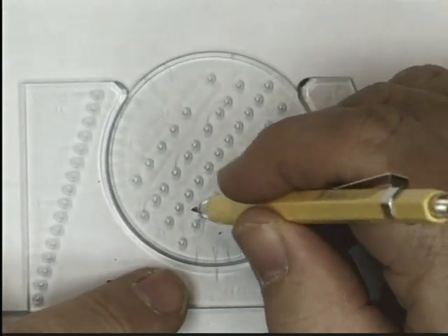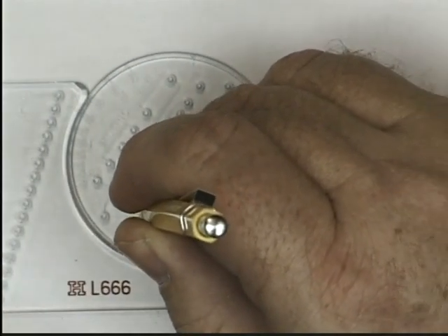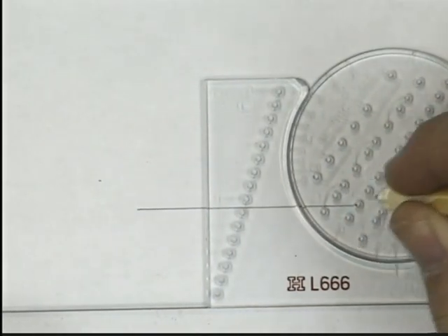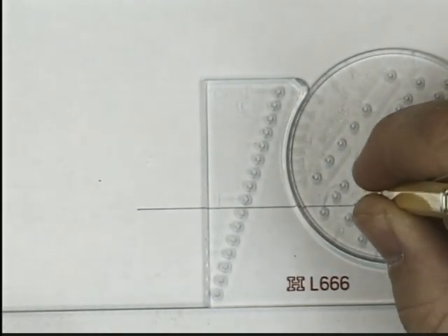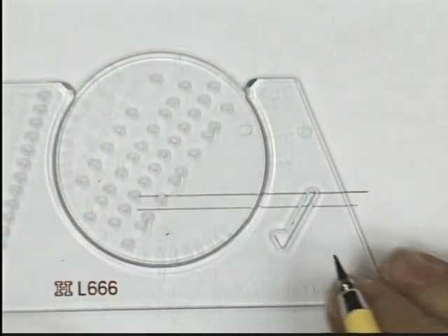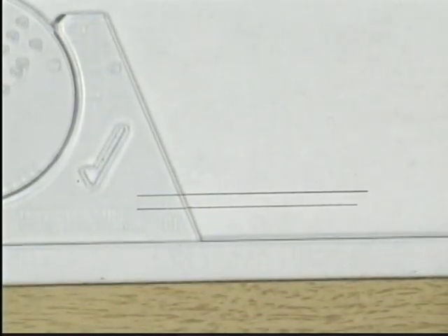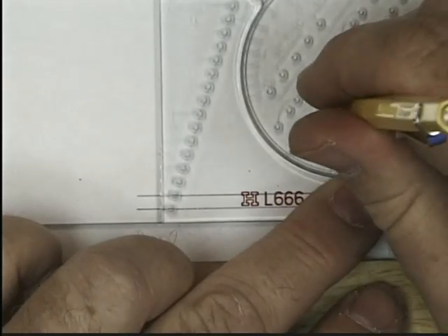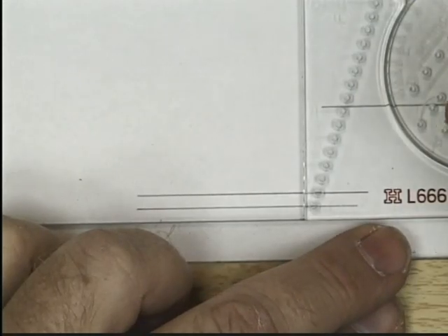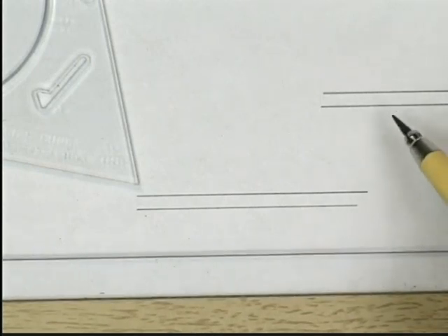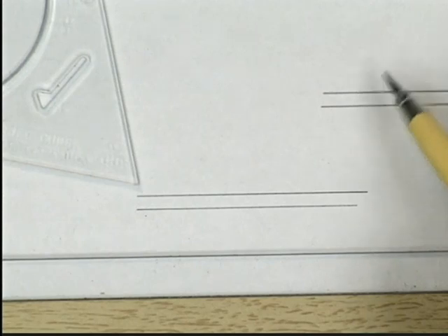The way I use this is I put the pencil in one of these holes, and then I run it across the paper, then I move it to the next hole, run it back again, and you can see it's made parallel lines nicely spaced. Then if I go off someplace else in the drawing and repeat that process, you can see again these lines are the same spacing. Now, again, I've made these darker than they should be. When you do this so light that if you're an arm's length away and you squint just a smidgen, you cannot see these lines because they're guidelines for lettering.